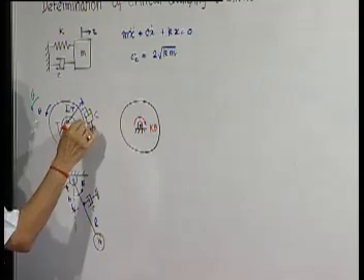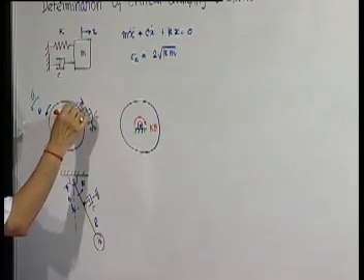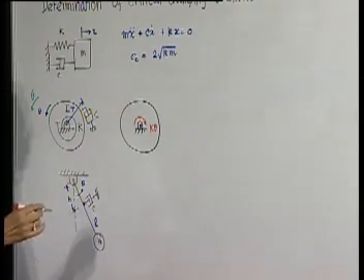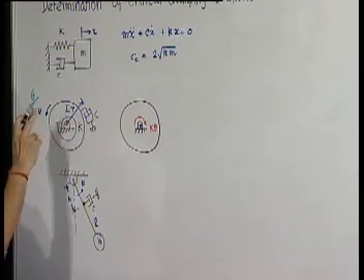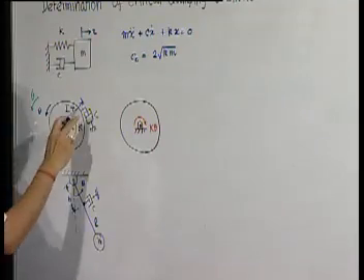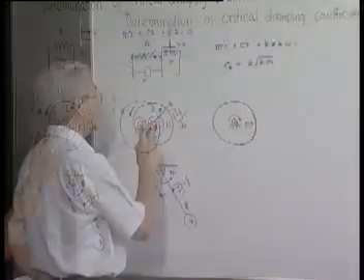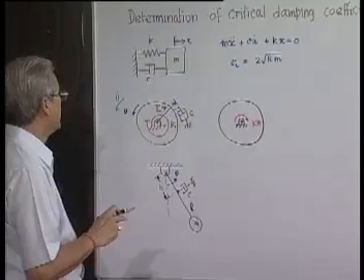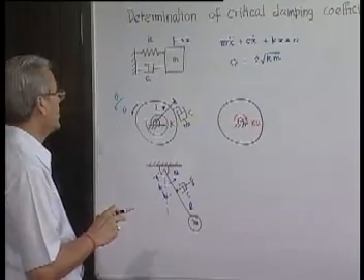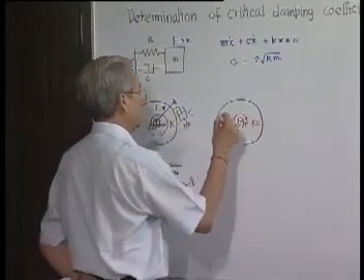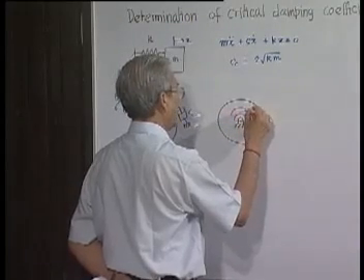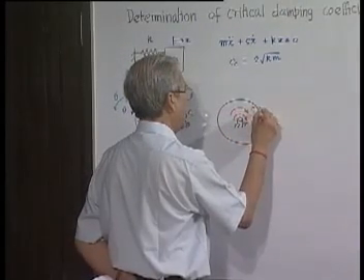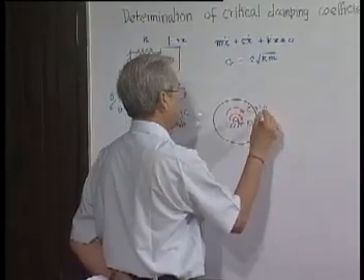The radius at which this damper has been placed is r. So, the linear velocity of the dashpot piston will be r into theta dot. So, the damping force will be c into r into theta dot, and its torque here again will be r square into theta dot into c. So, again there will be a resisting torque, it will be c r square theta dot.